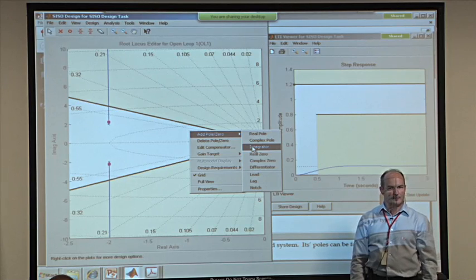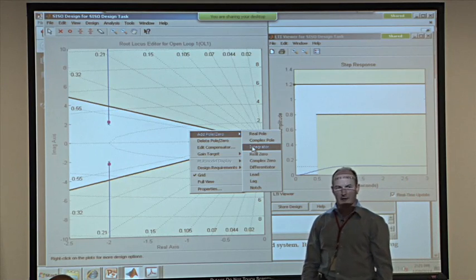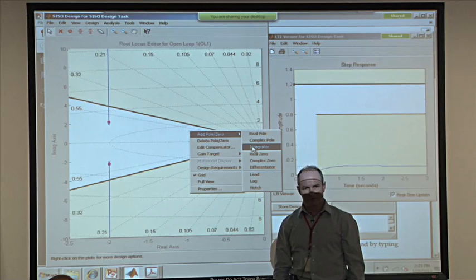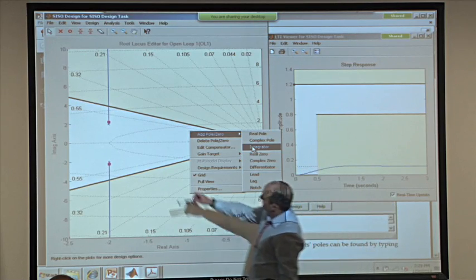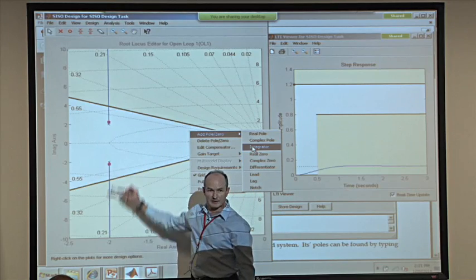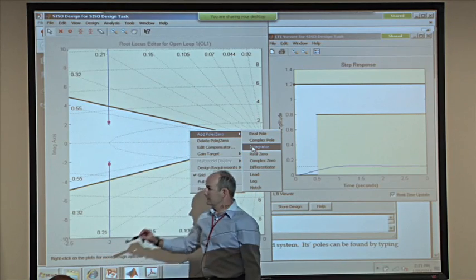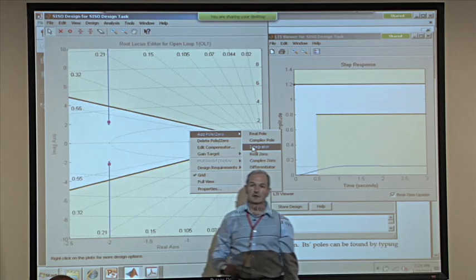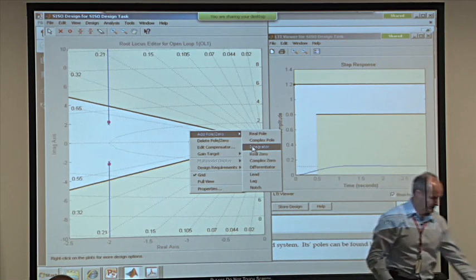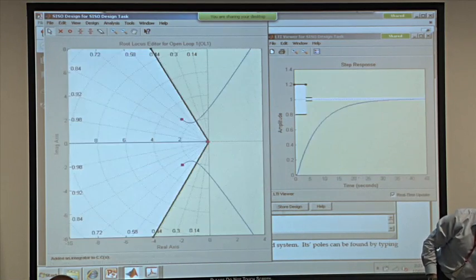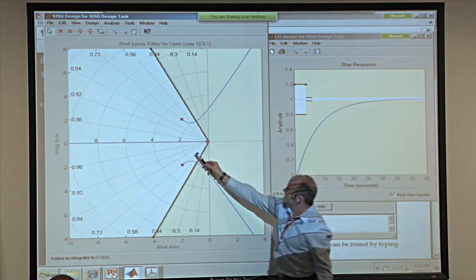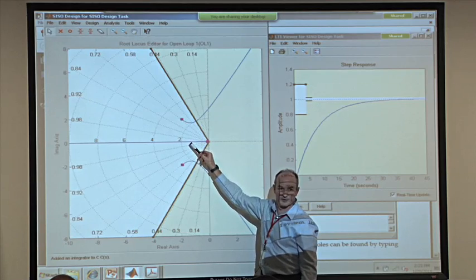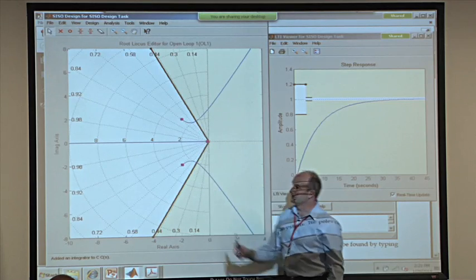Well, we now have a relative degree of 3 poles in the open loop, no zeros. So now, instead of having high gain asymptotes separated by 180 degrees, there are going to be 3 of them, and they're separated by 120 degrees, right? It'll look like that, okay? There are the 3 high gain asymptotes. There's one, there's another, there's the focal point, and there's 120 degrees between them.